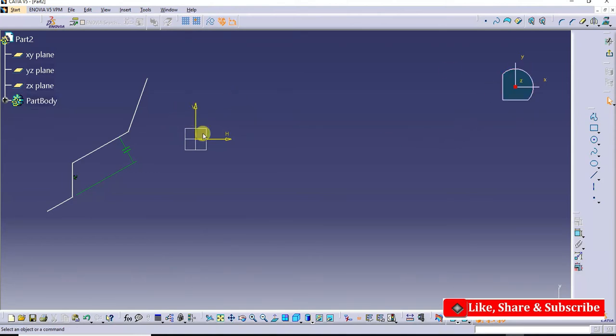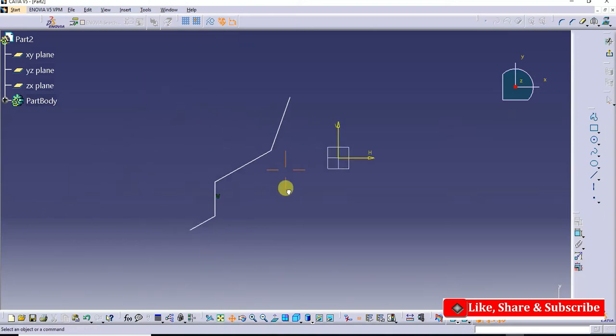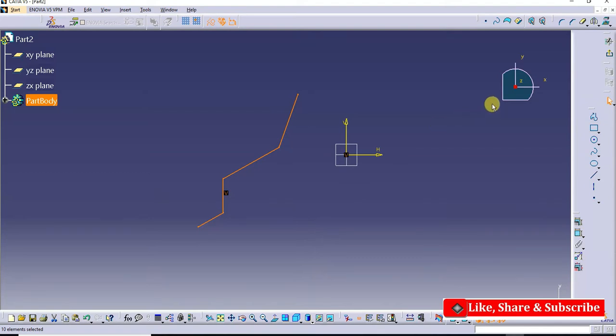How do you do it? I'll select the oval sketch, then I'll go for mirror, then I'll click over the axis. So this is the usage of the mirror command.